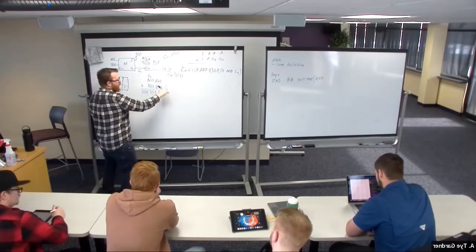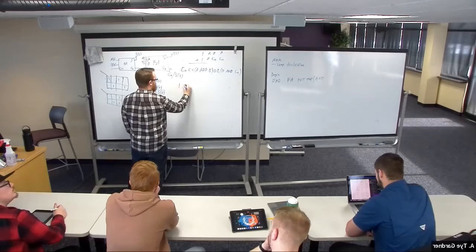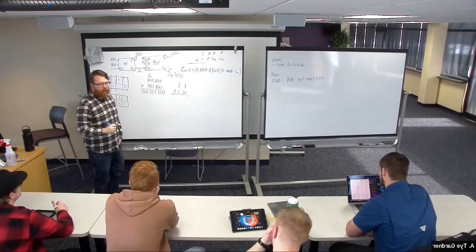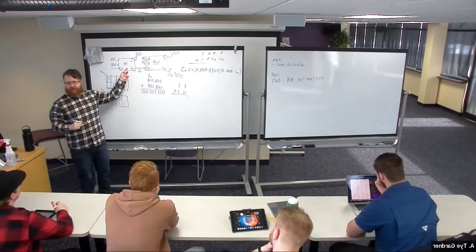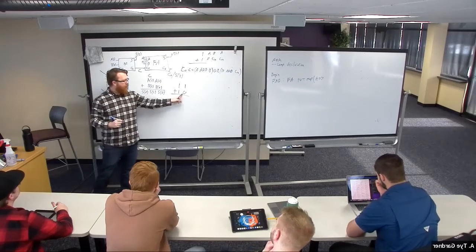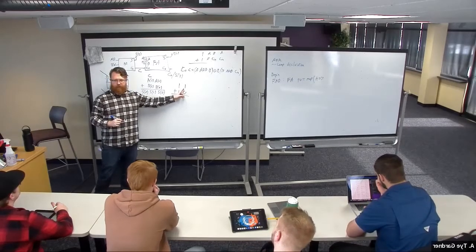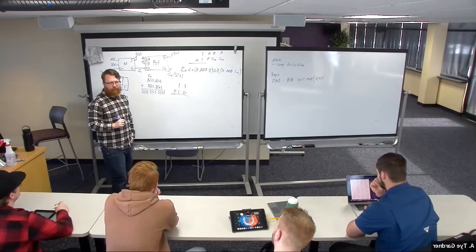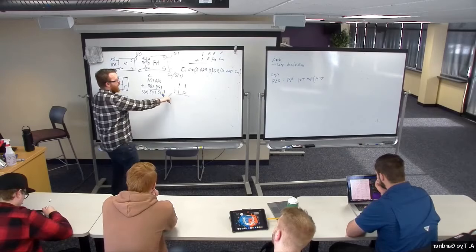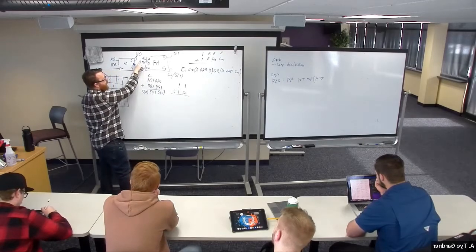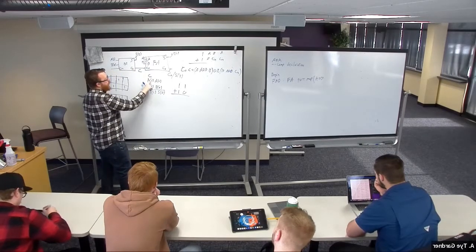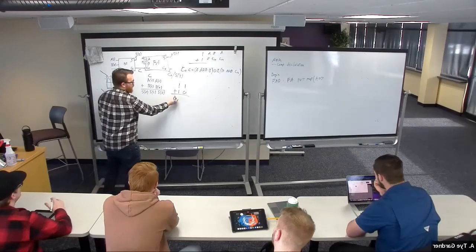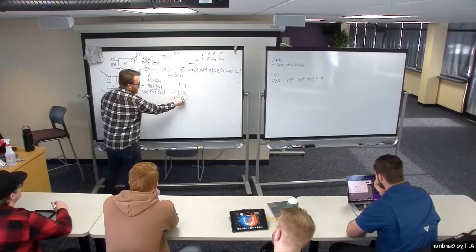So if this is here, 1, 1, 1, 0, and I do this addition, then the first full adder is going to add those 2 together, which is 0. So that means C is 0. Then it adds 1 plus 1, because A at 1 is 1, and B at 1 is 1. So then it's 1, 0, 0.